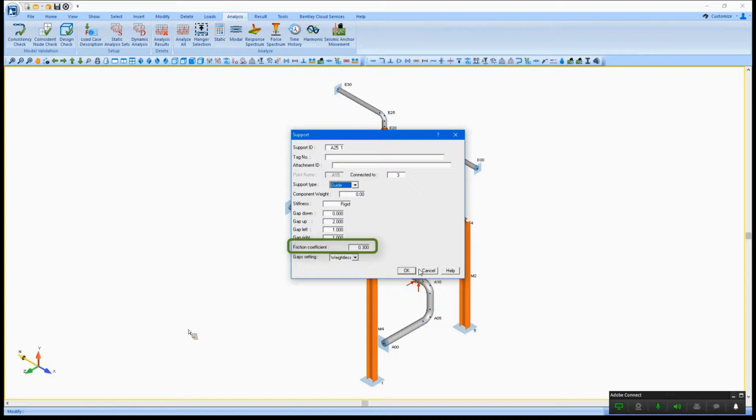And so it's really just a lot of engineering judgment. Just because they're being reported as inconsistent doesn't mean it's not acceptable to look at some of the results with that case. It just means that according to AutoPIPE's load sequencing, it's not consistent with AutoPIPE's load sequencing. So that's when you have to, as the engineer, decide, okay, let me really understand what this load combination or load case is, and can I really use it to review my results? So it kind of just is a warning to you to take a deeper look at that combination and to understand if it's acceptable or not.